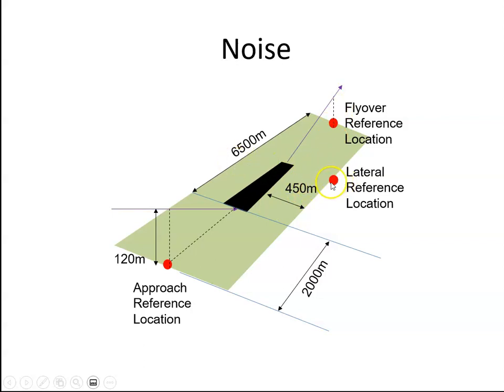All these noise measurements are taken at these locations, and then it's put into a computer, and the equivalent perceived noise measurement is then calculated. So you can't actually measure the EPNdB. You just measure the normal sound, and then a computer algorithm will convert the decibels into the EPNdBs.